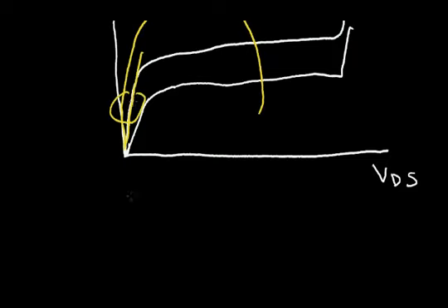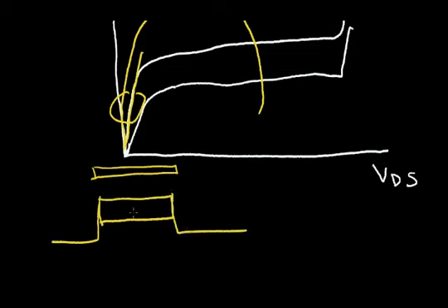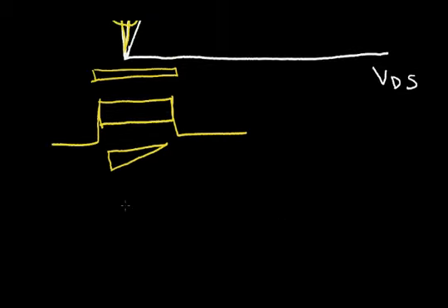And in this part of the curve, you can think of the channel as this being a bar of silicon, where the gate electrode is up here and the source and the drain regions are here. So now in this part of the curve, the channel is more like this. It gets pinched off. And over here, the channel is deep over here and will even pinch off sooner.